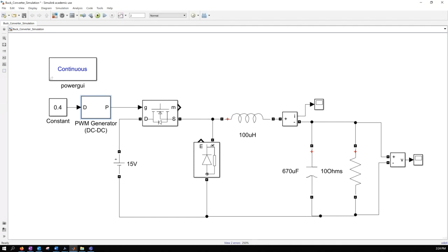So that means it's the same, and then the differential equations cannot be solved unless you run the simulation faster. So essentially, if you have a certain frequency in your Simulink model, you have to run the simulation much faster, typically 1,000 times faster or 100 times faster, especially when you run fixed step.